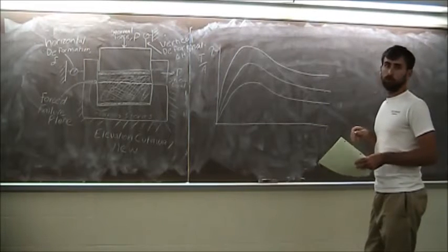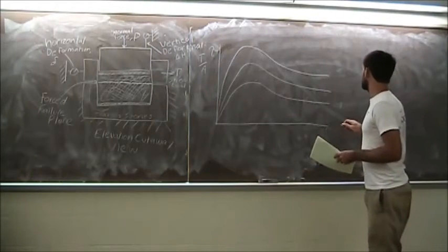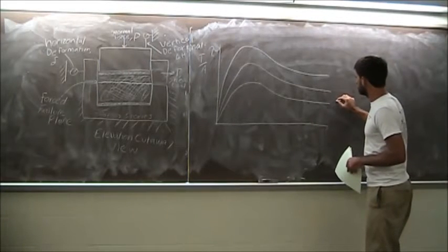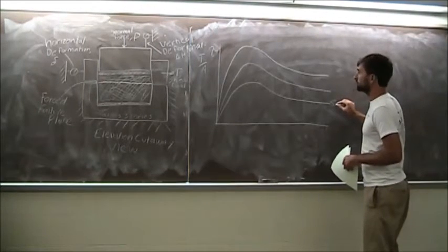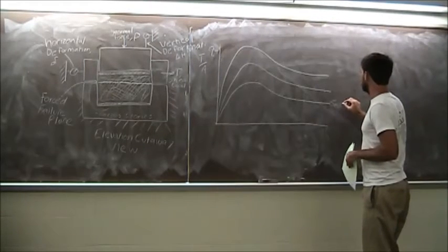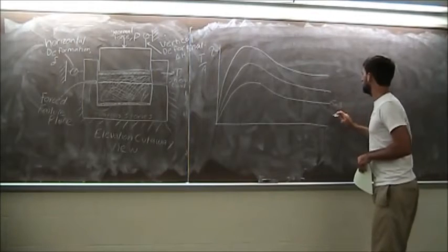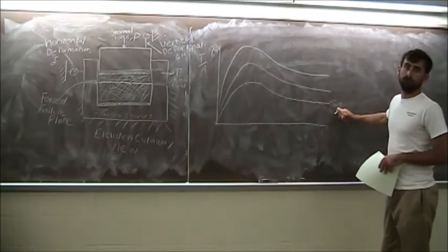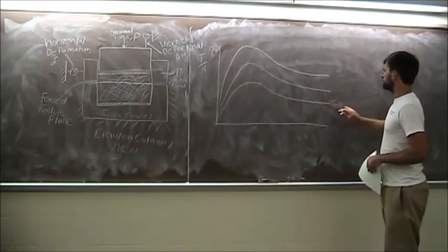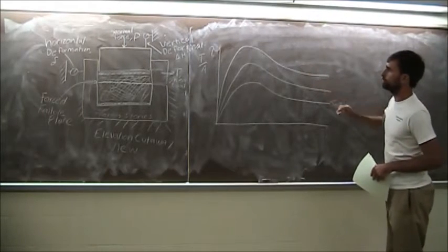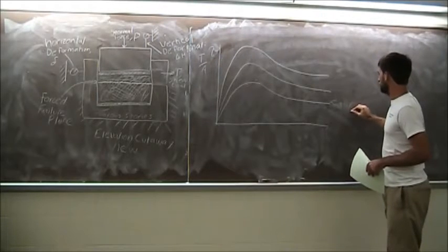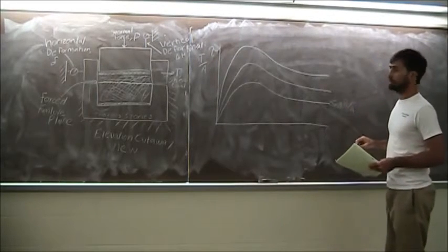But you need to figure out the normal force as well. We'll call this sigma normal 1, which just differentiates it from the first, second, and third test. So for sigma n1, it's the normal force, which is P, and that'd be P1 for test 1, divided by that nominal area that we talked about earlier.